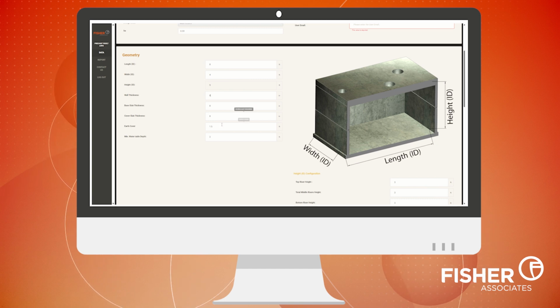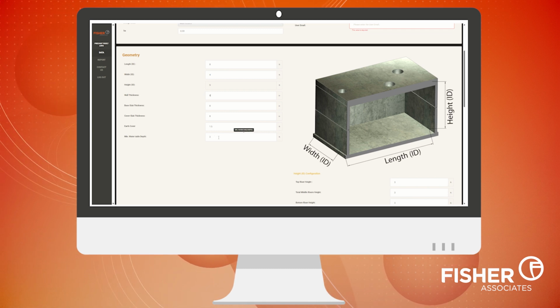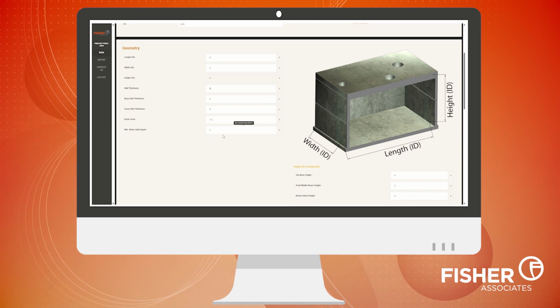The earth cover refers to the depth of soil above the vault. It can range from 0 to 1.5 feet. Next, enter the water depth, which is the distance from the ground surface to the water level. For this demo, set it to 2 feet.